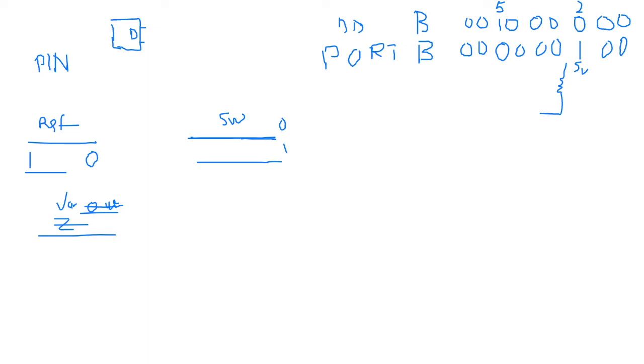Now we know that each time we do a shift to the left, we are performing a multiply by what? 2. And we can simply pick the very bit we are interested in by using the power. So if you are interested in bit 5, we can simply jump straight to 5. Or with regards to what we wanted to do today, you can actually use pin D5, but there's no fun in that. It's just a bit. Anyway, we'll get back to that at some other point. So if you want to shift to bit 1, you can just simply use a 1 there.